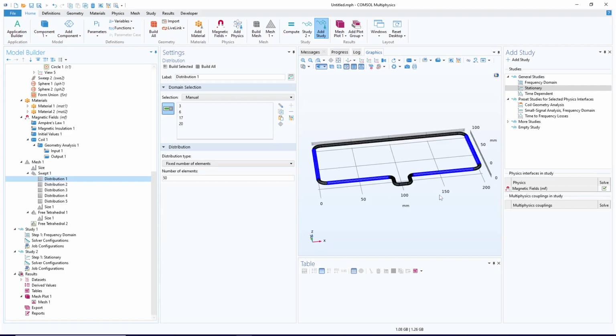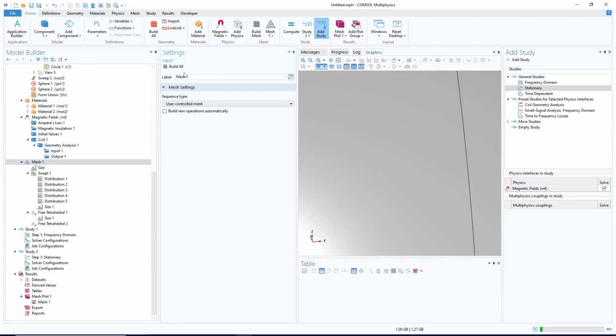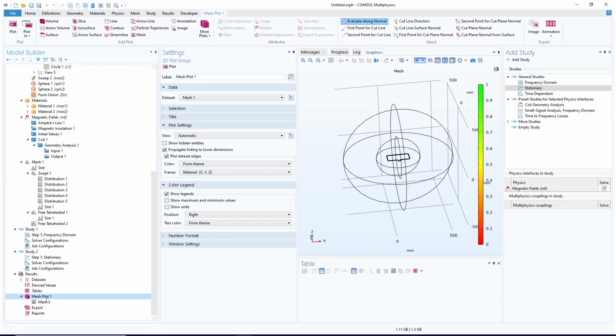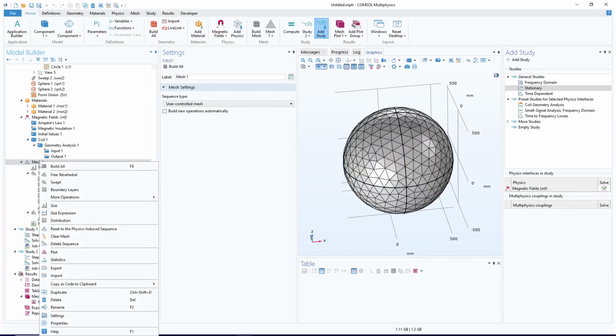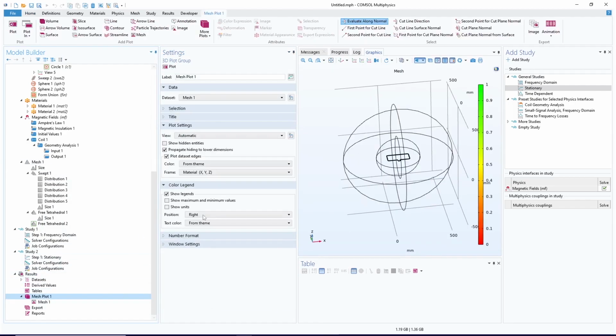This distribution was for these sections. So I'm going to change this, maybe put it to 60. And I bring everything back so you mesh it. Then we can check the quality again to see if it has improved or not. So you repeat this process several times until the quality is as you want. Then you can proceed. Of course, in this case, the original was very good, so now the quality even improves to 0.20.